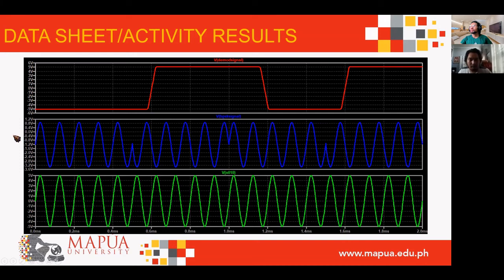That is the output from the BPSK modulator circuit, which is then fed into the first phase along with the carrier signal, then the output from the first phase is fed into the second phase. We get the output of the demodulated signal, which is the red labeled graph. As we can see, the original binary signal is recovered by using the demodulating circuit.